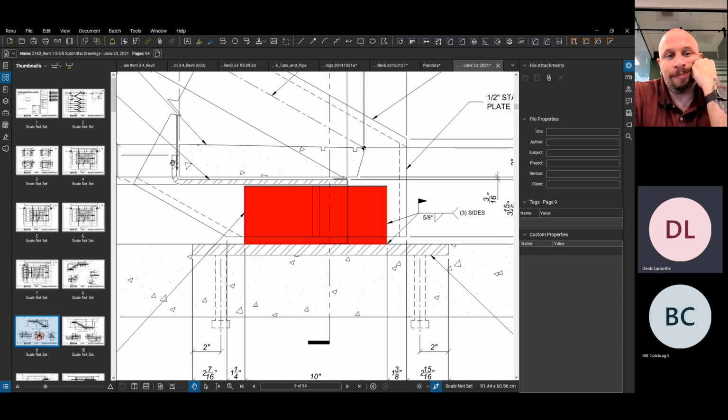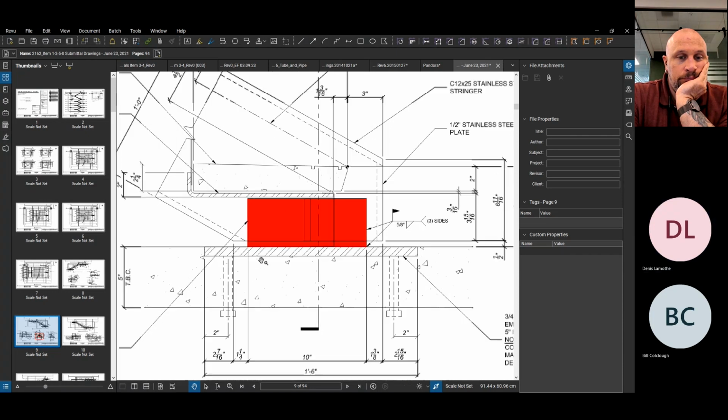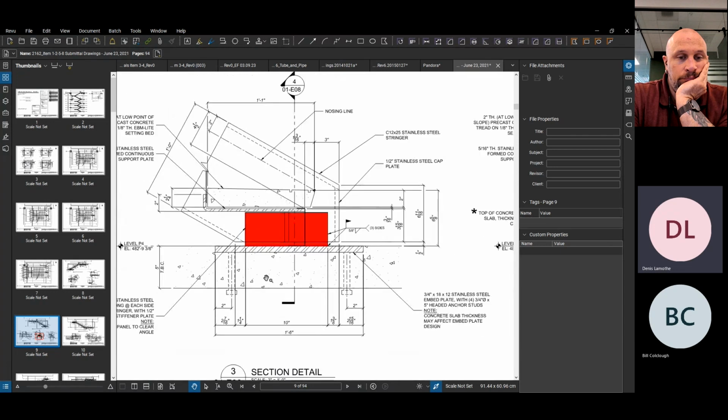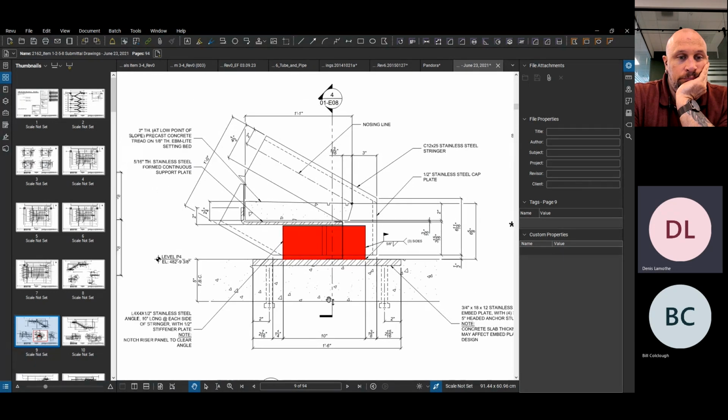And then they'll just come back after the fact and they'll just tack on and re-weld the treads and riser plates back in position for that one section as needed. That might also apply at the top connections depending on how much room there is to work with. So those would be the two main connections if we consider a stair on top of the slab.